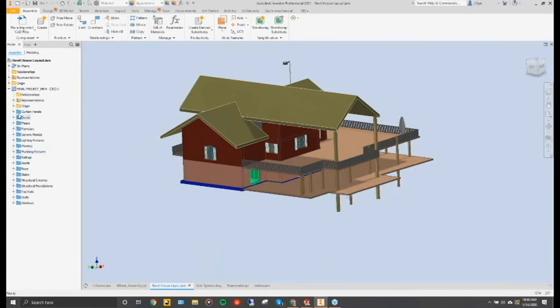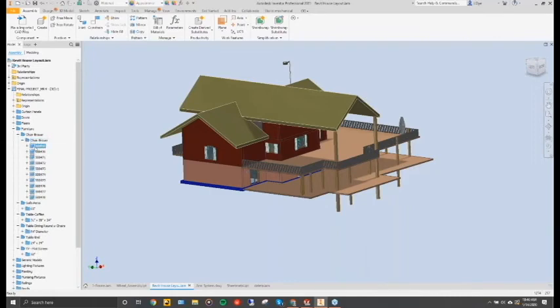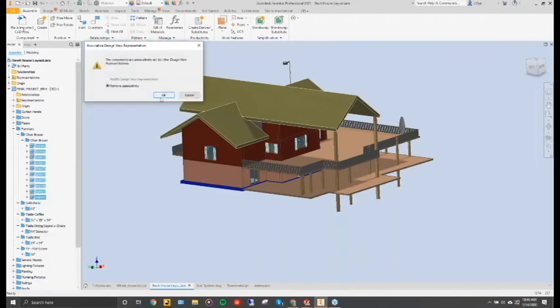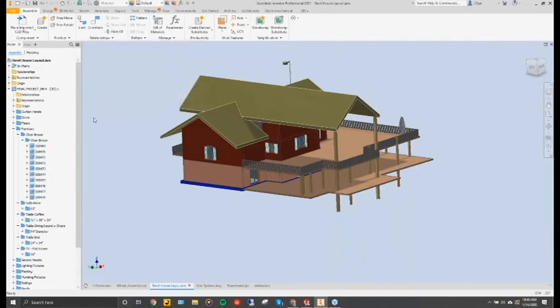Look at my model tree. You can also see that there are folders set up. These folders are fairly similar to what you would see in Revit, in regards to, there's a folder for furniture. So this Revit file has many different types of furniture items in the design. As mentioned, I could come in here and right click, maybe turn the visibility off of some of these components and so forth. We're just removing associativity right now. Okay. Select those, right click, turn visibility on.